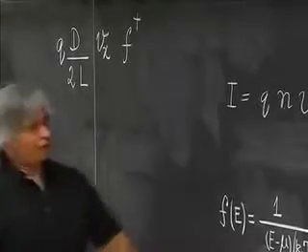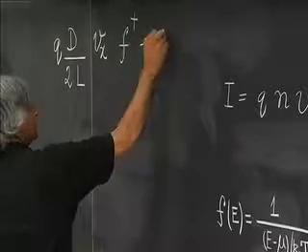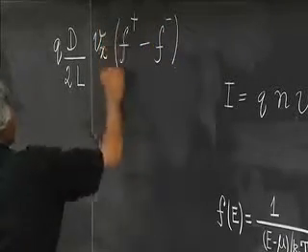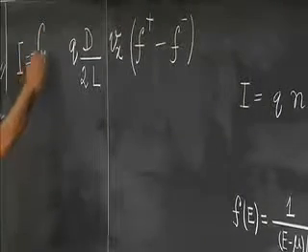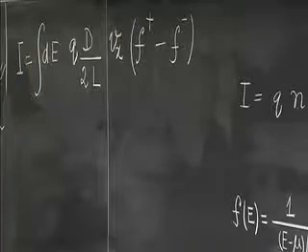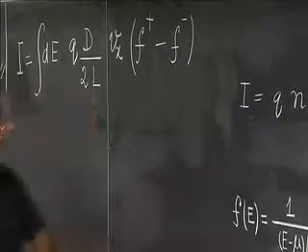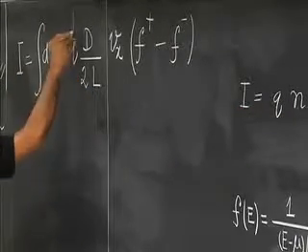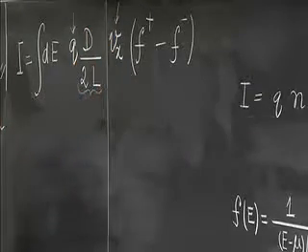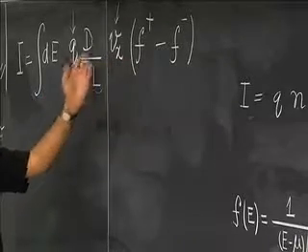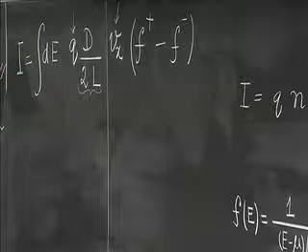And then there's the negative-going ones. Those are also filled a little differently. And that's why the current is the difference between the two. And you could write it this way: I is equal to the integral dE. So this is at a given energy. If you just looked at Q and V, you'd get Q times V, this times this, that's the N. And you have things going from left to right, and you have things going from right to left. And the difference, when you sum it over, gives you the current.